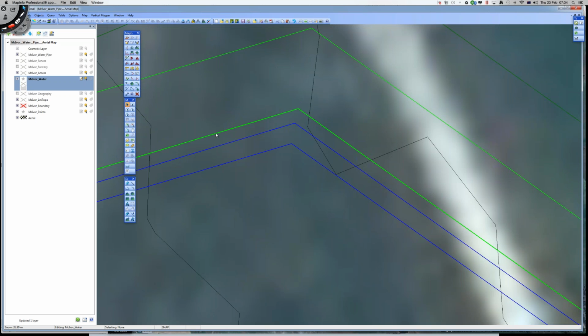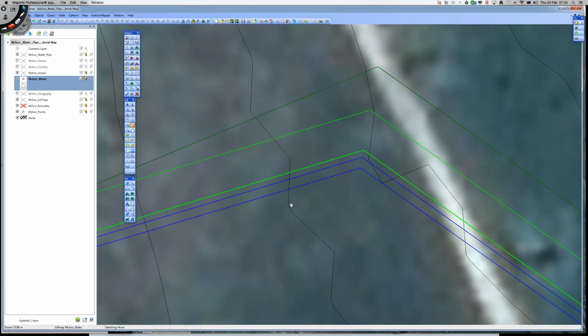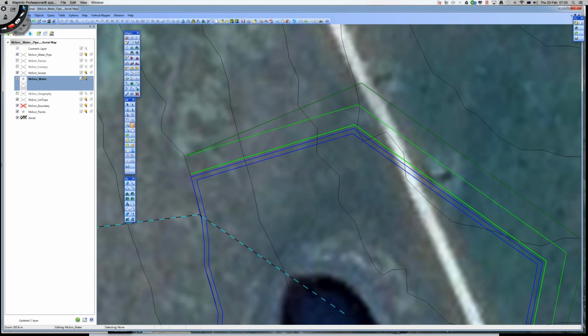Now you can see here, this is a good illustration of what's gone on. We've got a 75 centimeter freeboard here. And so the distance between here and here, because it's a 1:1 slope, is a 77 centimeter distance, whereas the distance between here and here is a meter. All right, so that just illustrates, and this is in a plan view. This won't create a 3D for you. This is just so that you've got some sort of indication of how the topo might work in this sense.